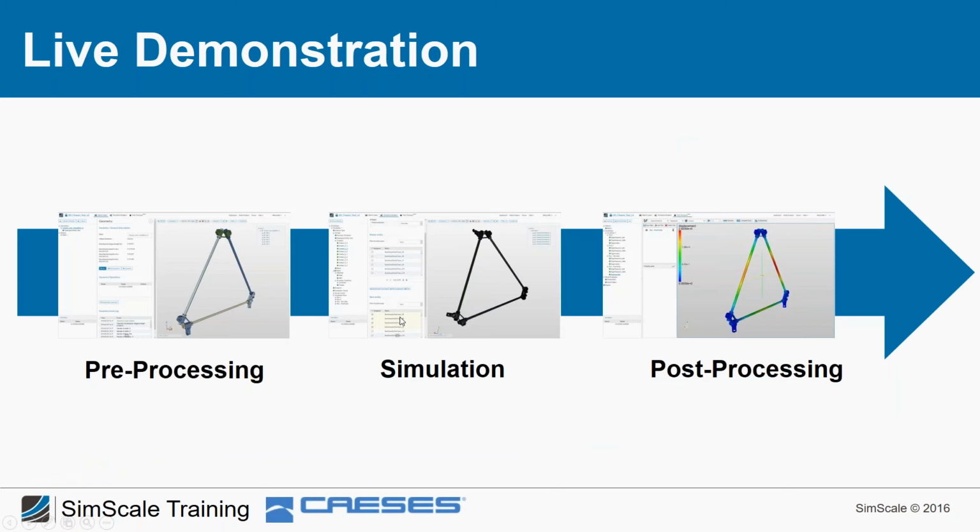And right now what we will do is we will open a project which contains the CAD model of the subassembly of the frame. We will first of all create the mesh like last time. So we will divide the volume of this body into smaller subvolumes, which are later on used to calculate in these cells stress, displacement, etc. Or in our case, not in the cells, but at the nodes.